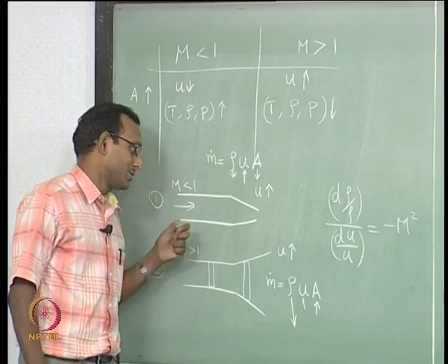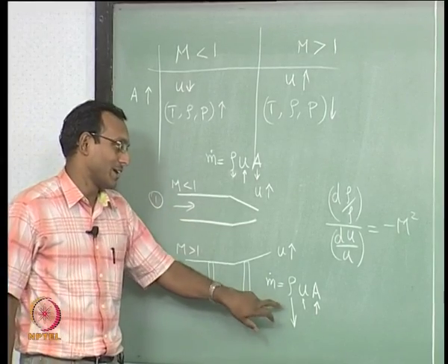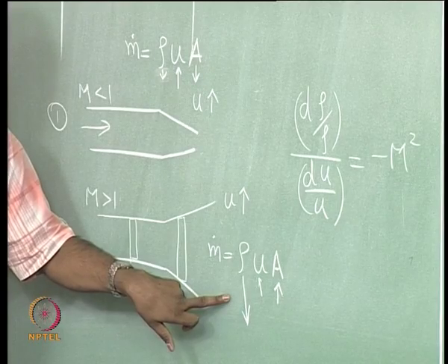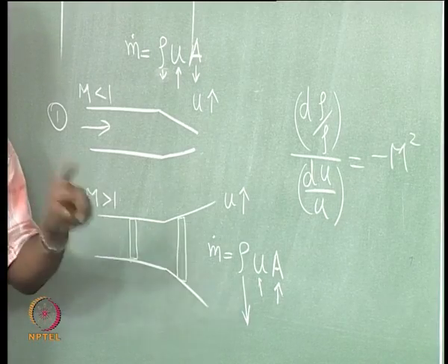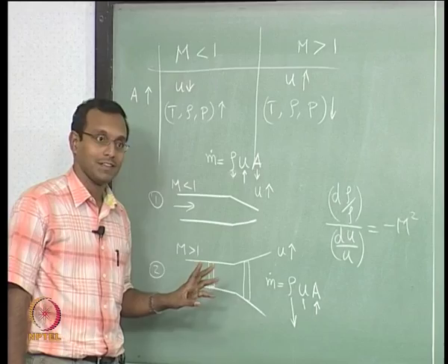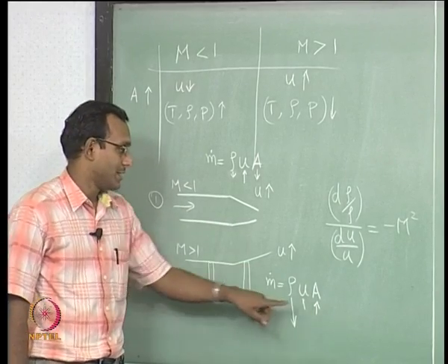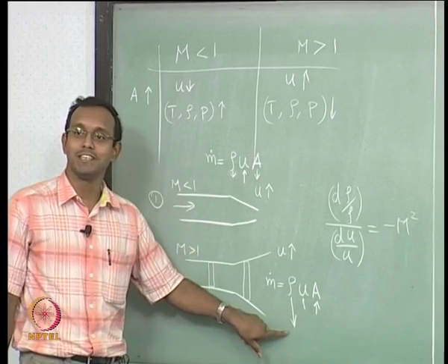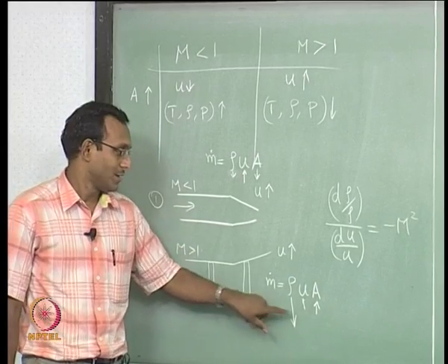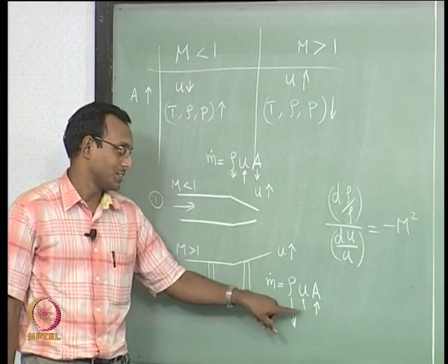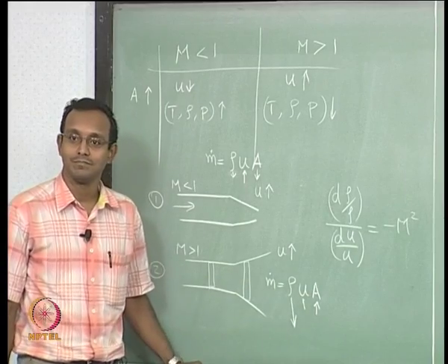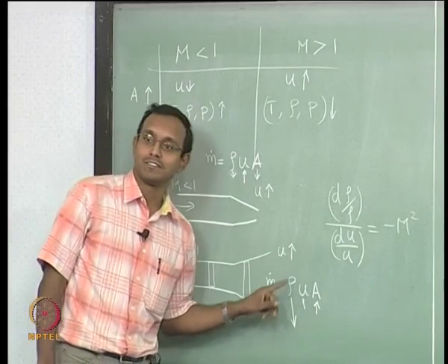Okay. So, this is a nice way of looking at what will happen in supersonic flow. If I suddenly change something, the first thing changes is density, and then only it will start changing remaining things. Okay. Area increased, it has to drop density to occupy it. Now, it so happens that it changes too much that this will increase slightly. That is the way we are going to look at things.